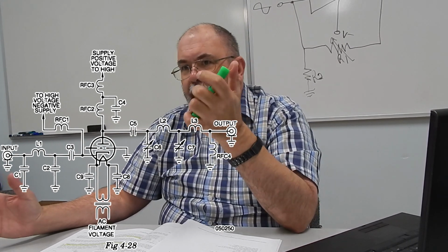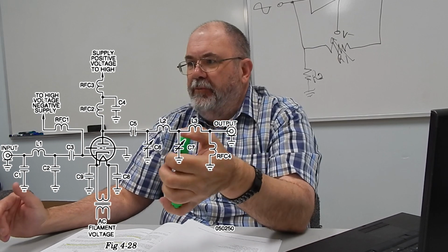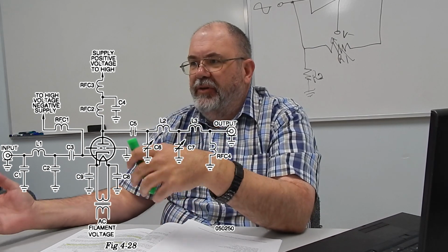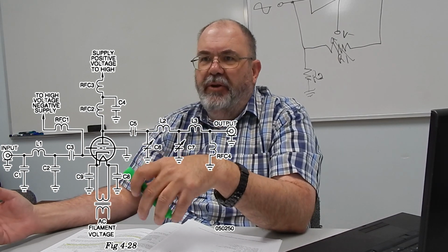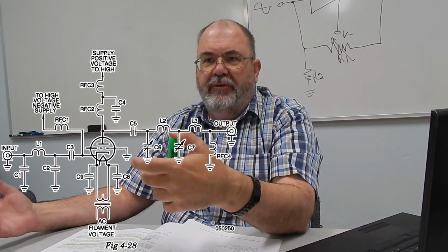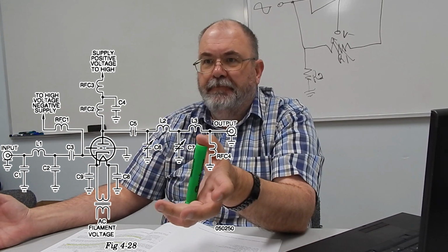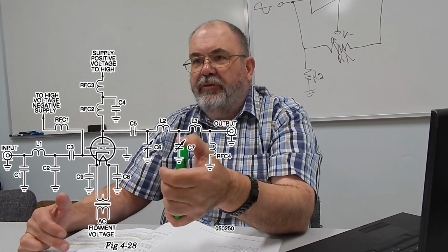Okay, now we haven't really started talking about antennas and transmission lines and all this, but almost all of our ham radio antennas are 50 ohm antennas. Okay. The output of this tube is in the order of a couple of 100,000 ohms. Okay.